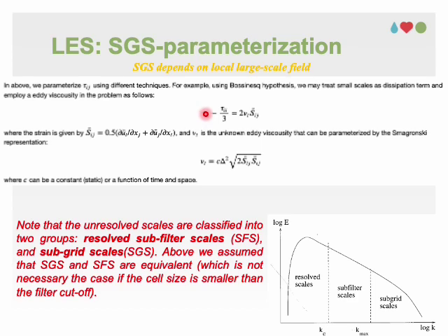The Smagorinsky model introduces a new turbulent eddy viscosity that determines the amount of energy that is dissipated by the unresolved scales and is determined based on the grid size and the local velocity gradients. It is noted that the Smagorinsky model cannot address backscattering of energy from small to large scales.